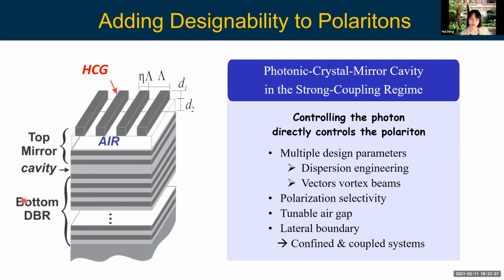And that's typically the case for the DBR cavities, and it's very involved in order to reduce the dimensionality. But with these gratings, we can just make the gratings as small as we want, as long as there are still maybe 10 periods or something. And then we effectively impose a transverse confinement. So that's what's happened here.